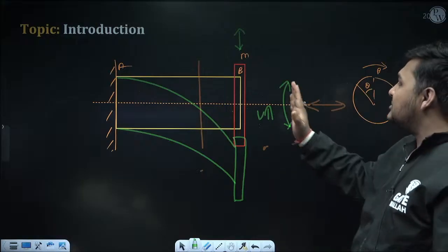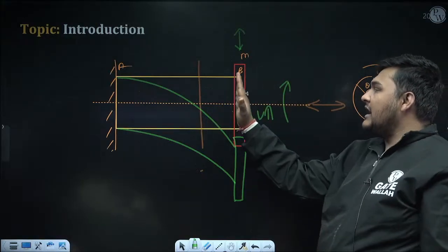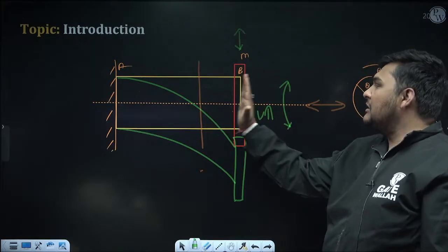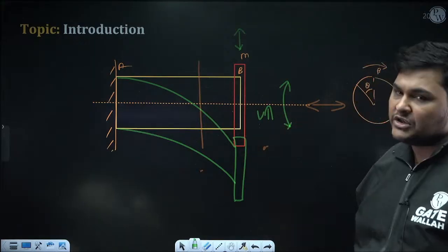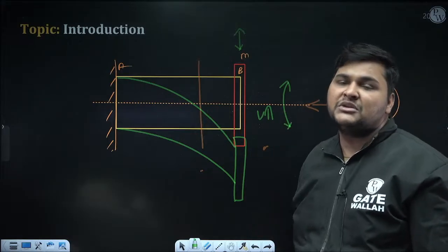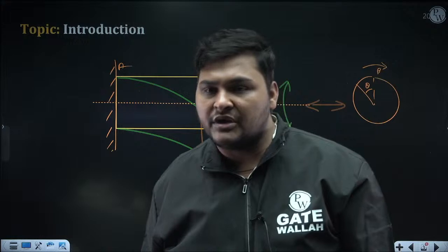So if I am disturbing the rotor like this in longitudinal direction, then releasing the force which I applied to disturb it, it will vibrate like this. This vibration is known as longitudinal vibration. In longitudinal vibration, axial stiffness of this structure is responsible for restoration.